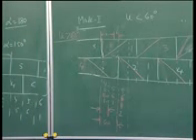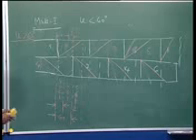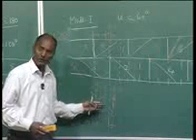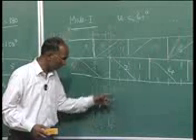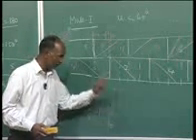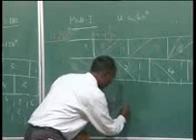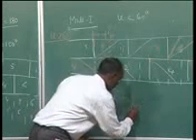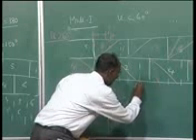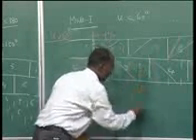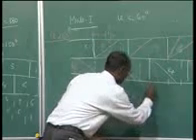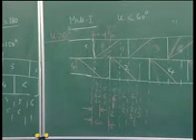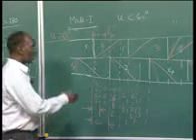So this sequence will follow. You can see this is also symmetrical: 4, 5, 6, 4 will go, 5, 6 will be retained, then again 2 is fired, then 5, 6, 1, 2, 5 will go, then we will find 6, 1, 2 and so on. I can write here 6, 1, 2, 3, and then we can go to 1, 2, 3 and so on. So this will be the conduction pattern. Now we have to see how much who is conducting.